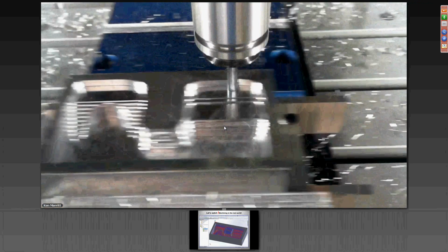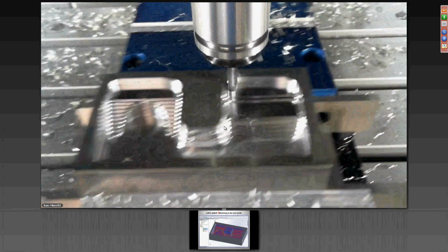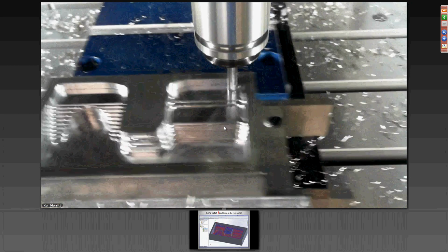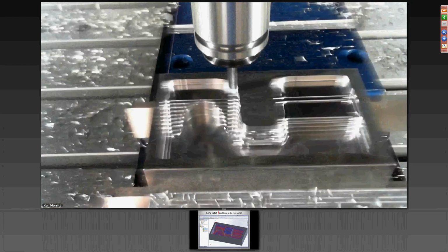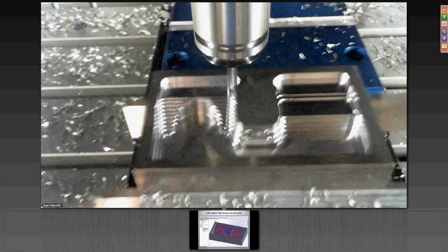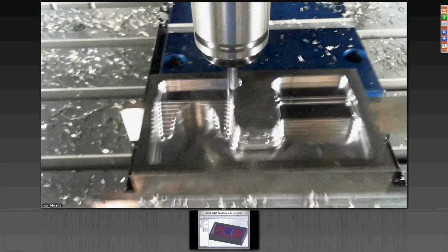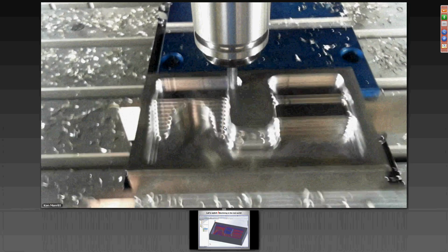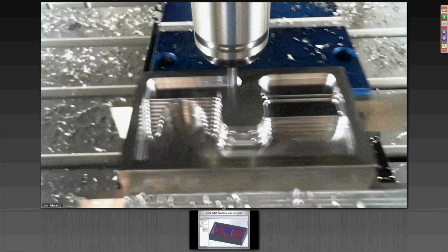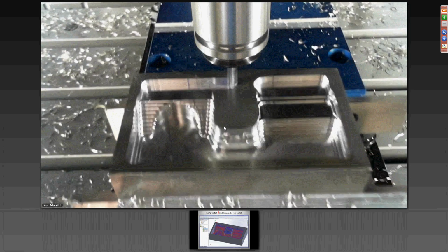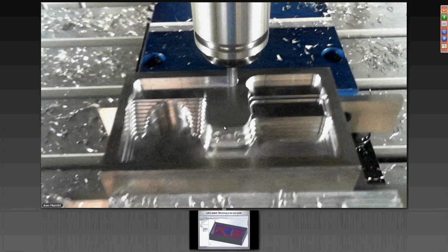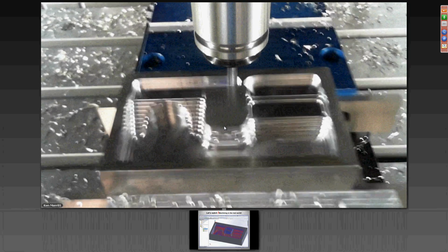Yeah, and that's kind of what I was explaining a bit ago about the repositioning moves. The way we can do that is what Brendan is talking about. We have a function called detour moves, and the user actually has control over this. You can specify the distance of a move that you want to be within the retract or within the detour. Okay, and so if the move distance exceeds the value that you set in the interface, then it'll go ahead and jump up to the rapid clearance plane and do a standard G0 movement.